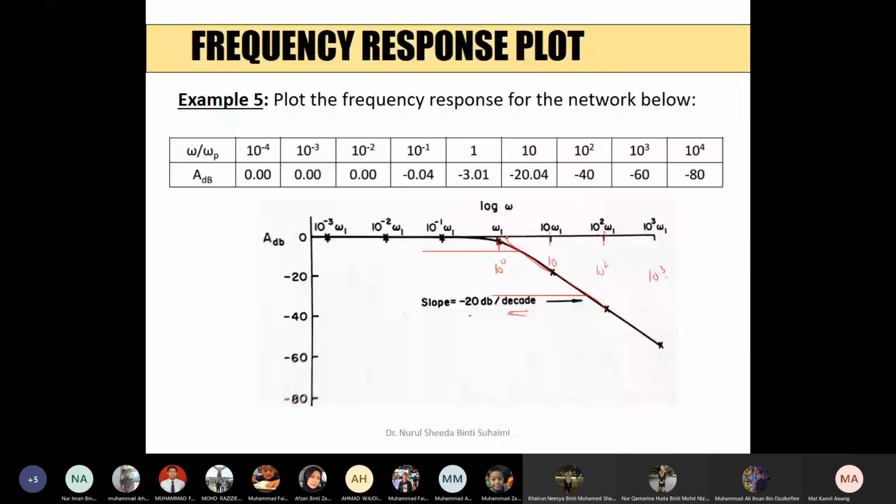Okay. So the Bode plot is basically a straight line here, and over here there is actually a drop of 3 dB. If it goes smoothly like that, over here is a 3 dB drop. You see this? It dropped 3 dB. That is 1 over square root 2.